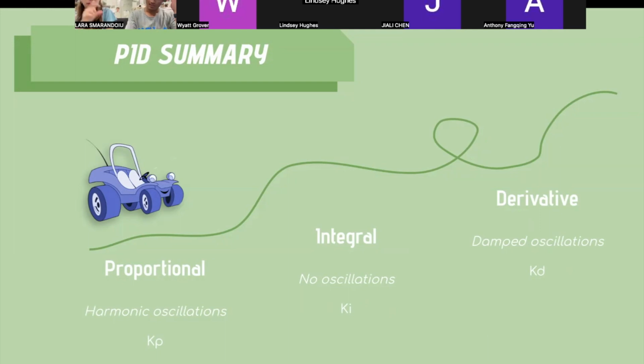Then for that error value, you're either going to proportionally change how you're moving, or calculate a derivative of the previous errors, or take an integral, basically just adding all the previous errors you've ever had and changing things based on that. So basically, you have your error and you just do separate calculations for each controller, and then you change, for example, for our cars, how fast we're going, or what direction you're going in.